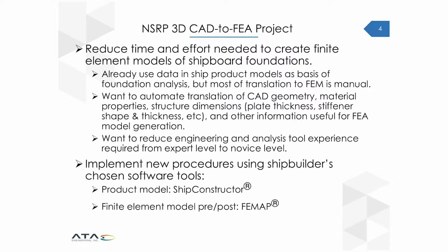In this case, we were working with Ingalls and their finite element tool choice is FEMAP. So this solution is specific to FEMAP. We did our best to make the whole process fairly modularized. So we separated the part that interacted with ShipConstructor from the part that interacted with FEMAP. So if someone came later and wanted to do this with HyperMesh or Nx or some other tool, it would be a relatively low effort to do that.